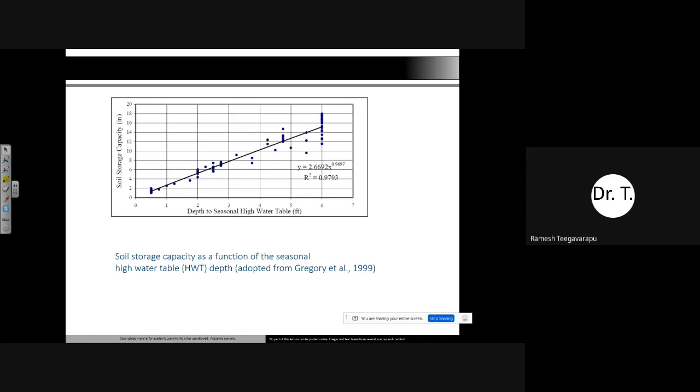So what does that mean? Ours is typically a wetland, which was restored to urban areas and so on, and we have a lot of recharge happening. We have a lot of rainfall, too many lakes, and all these things, and a sandy type of soil will contribute to what we call high water tables. So whenever you are looking at the water table below the soil, that water table influences the soil storage capacity. So this is the problem.